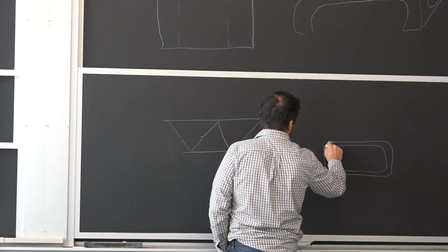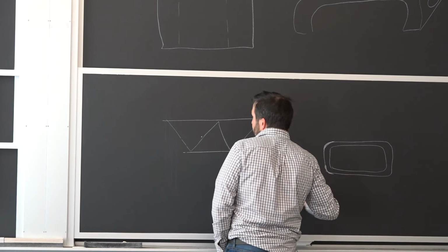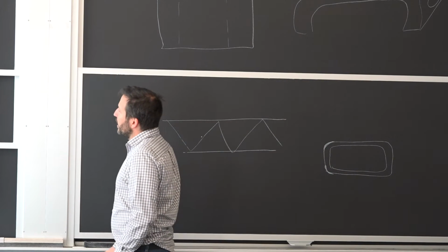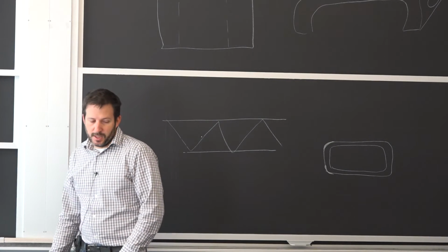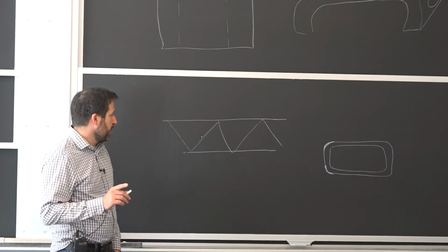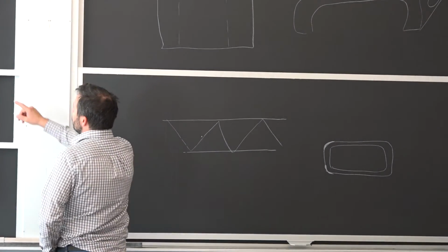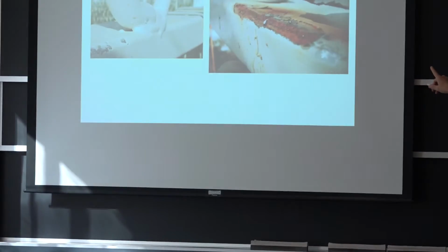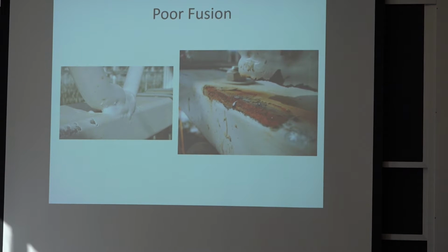This has the same shape here where it broke as the other side. So visually, without going into too much detail, it's a lack of fusion. Now, there's another reason why you can tell that it's a lack of fusion: when you look at the upper part there, you can tell that it was coming at an angle with the surface.